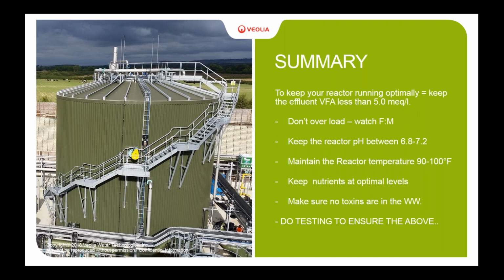Another thing is overloading your system. If you're tracking your influent flows and CODs, you know what your daily load is and what the system should be able to generally handle. If you come in and your VFA measurement is high, and your pH and temperature have been good all night long, the first thing to look at is: what came into the plant yesterday? Did my load double? Did my load triple? That's something you need to monitor.